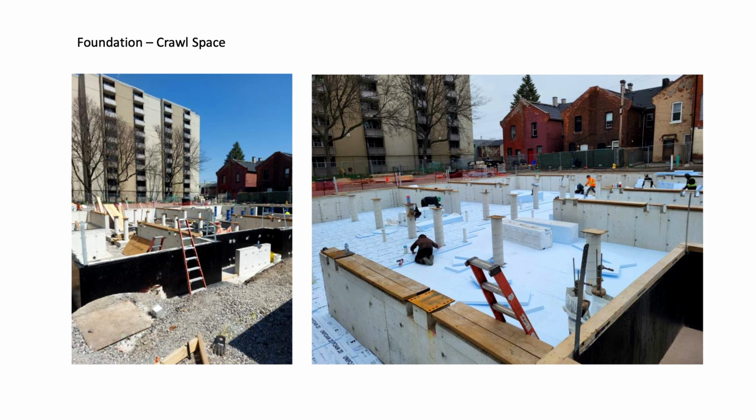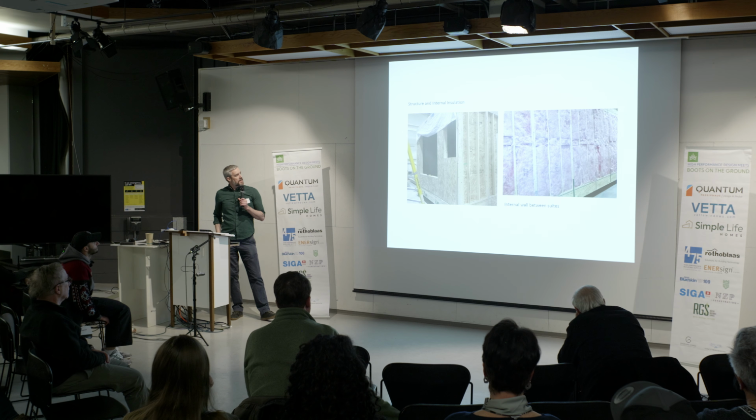So some photos then of the build itself. This is the below grade works with the insulating. You need that continuous line of insulation and continuous membrane around. So that's a shot of that.